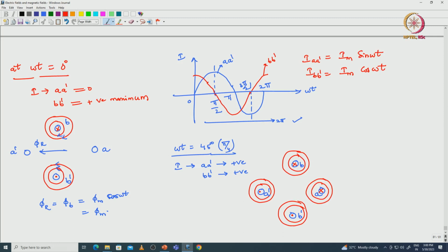Apply the simple thumb rule and identify the direction. With respect to the cross, we can say clockwise direction, and for the dot, anti-clockwise. So these two flux loops, loop 1 and loop 2, are in an additive manner, and the other two loops are also additive because of the flux loop directions, and the resultant flux vector is in this direction, phi r.